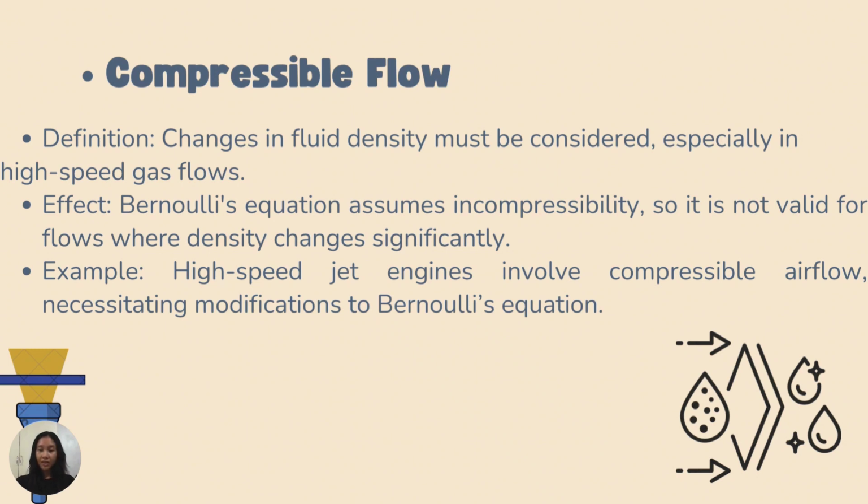Therefore, Bernoulli's equation cannot accurately describe compressible flow conditions and requires modification or alternative approaches. So, for example, high-speed jet engines involve compressible airflow due to the high velocities and temperatures associated with jet propulsion. As air enters the engine intake at high speed, it undergoes compression, leading to changes in density, pressure, and temperature. In such compressible flow regimes, Bernoulli's equation alone is insufficient to describe the flow behavior accurately.